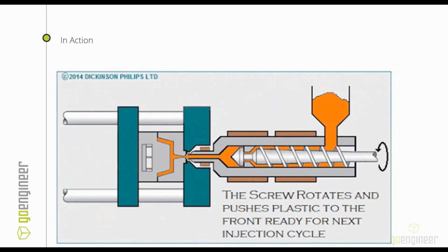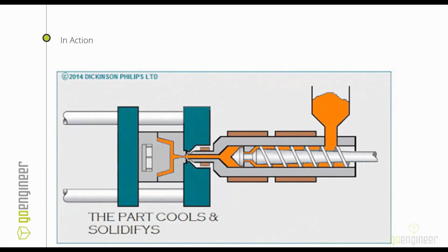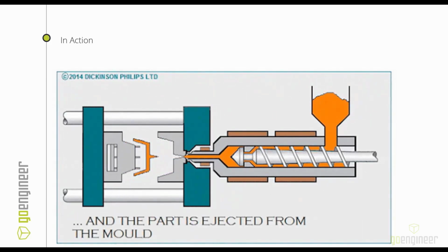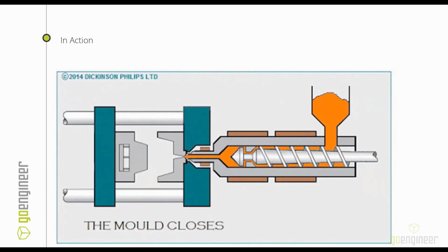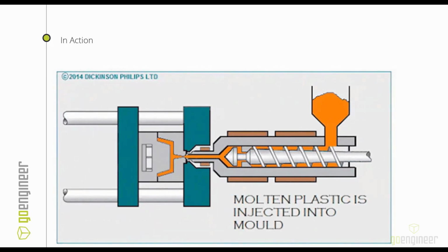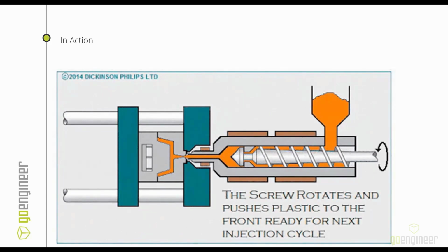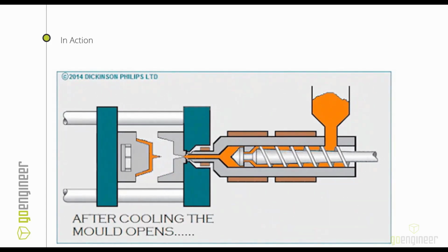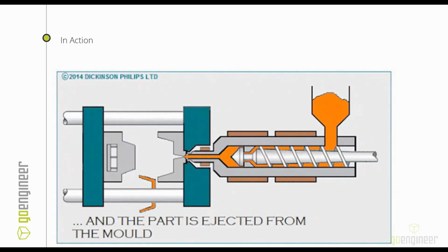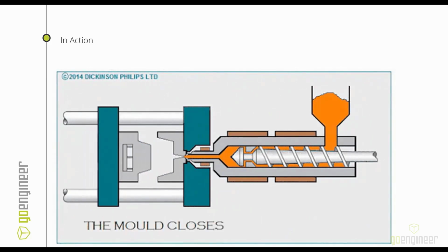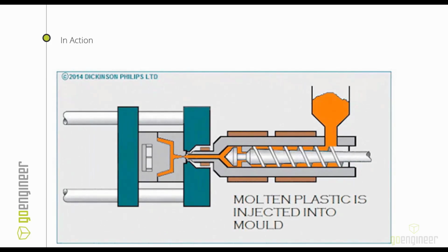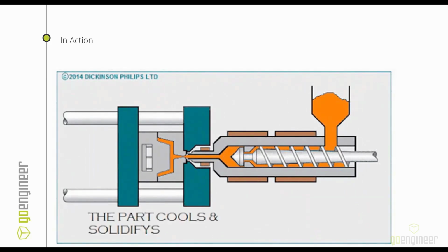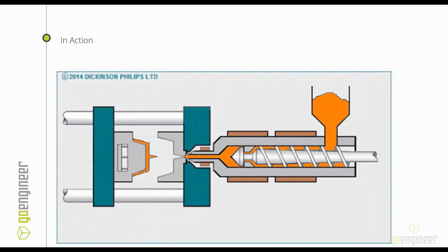So you have your auger that spins and pushes material forward and melts it, and then also uses the ram to inject your material into your cavity at high pressures and temperatures. It fills it up, allows it to sit for an X period of time to cool off for the plastic to re-solidify, and opens the mold back in half. It's generally the cheap molds; the cheapest ones you can get away with are 2-part molds. And then once it cools off enough for it not to deform, it opens up the mold, kicks it out, closes it, and starts it over again.